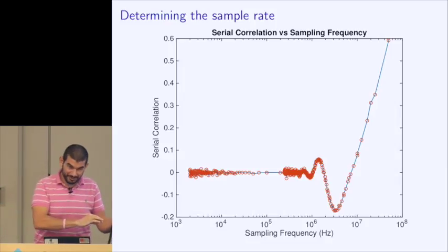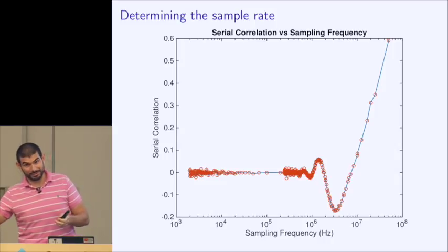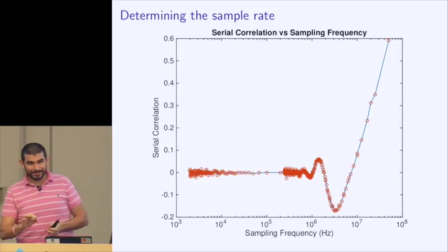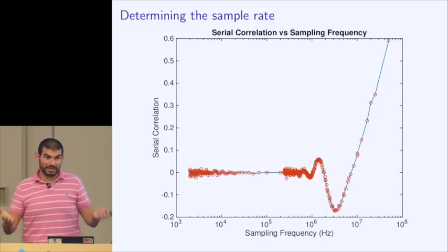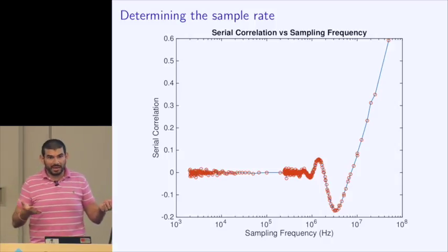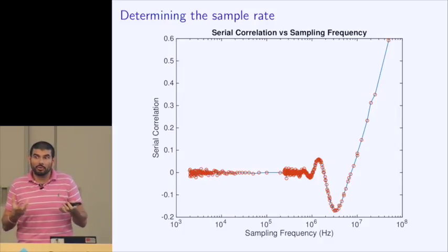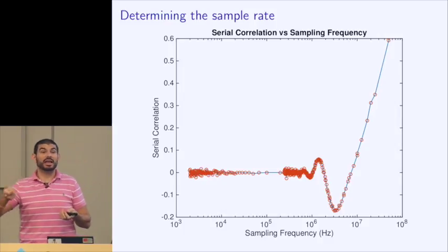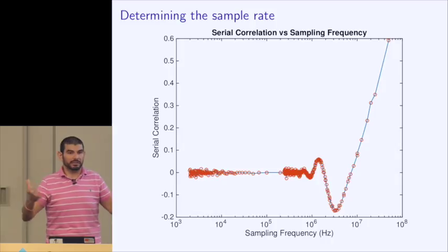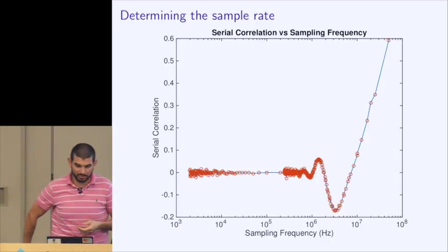We believe device physics, and therefore we believe that the noise source is okay. We're using the statistical tests to make sure that the circuit is operating correctly. So if the circuit were bad, we would see really bad, low entropy output, even though we know that, of course, the behavior of the avalanche breakdown itself is highly unpredictable and highly probabilistic.